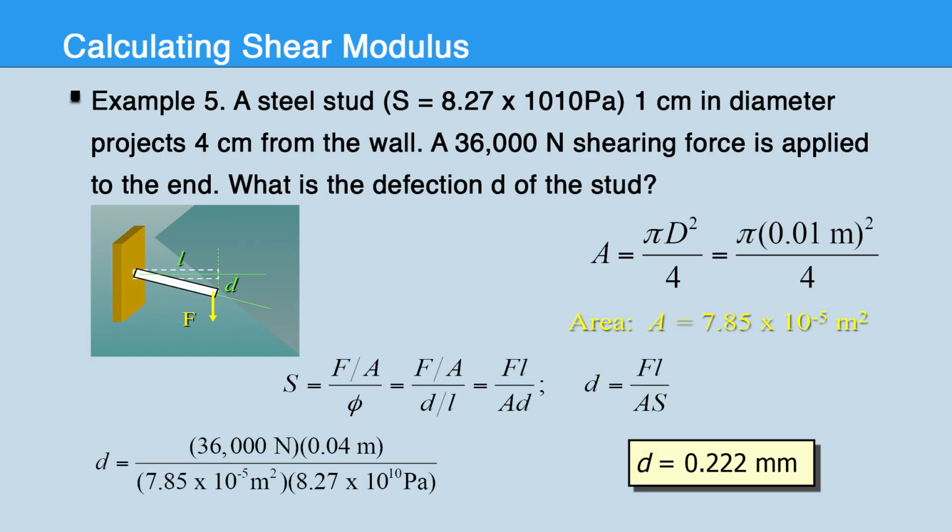Significance of the shear modulus. Rigidity indicator: the shear modulus indicates how resistant a material is to shearing deformation. A higher shear modulus means the material is more rigid and less prone to shear deformation. Design parameter: engineers use the shear modulus to analyze and design components that experience shear force, such as beams, fasteners, and other parts of buildings.